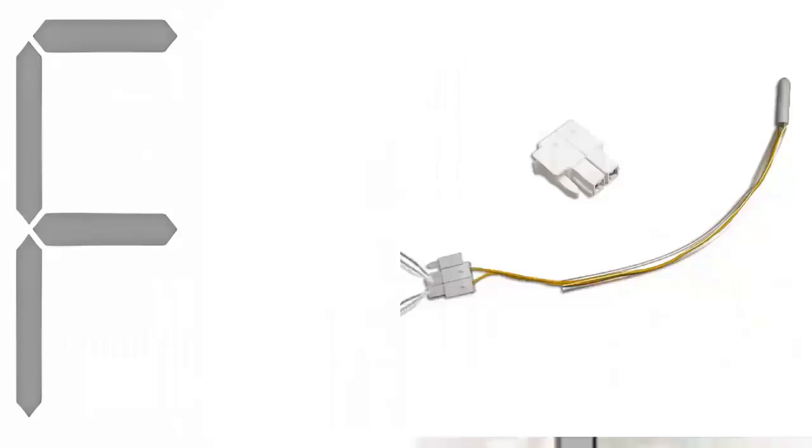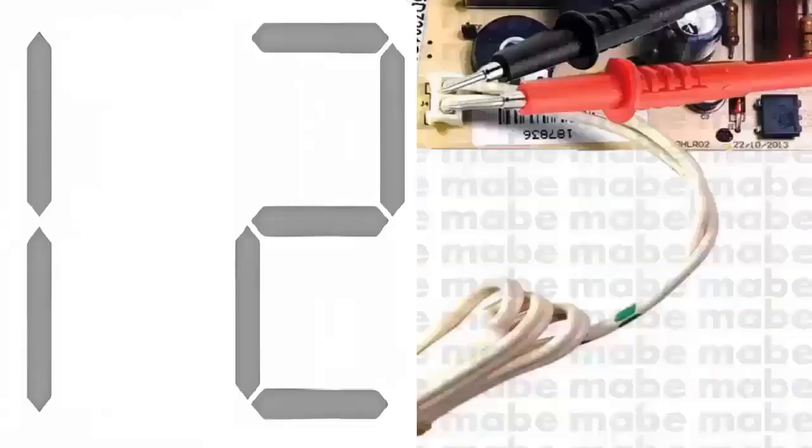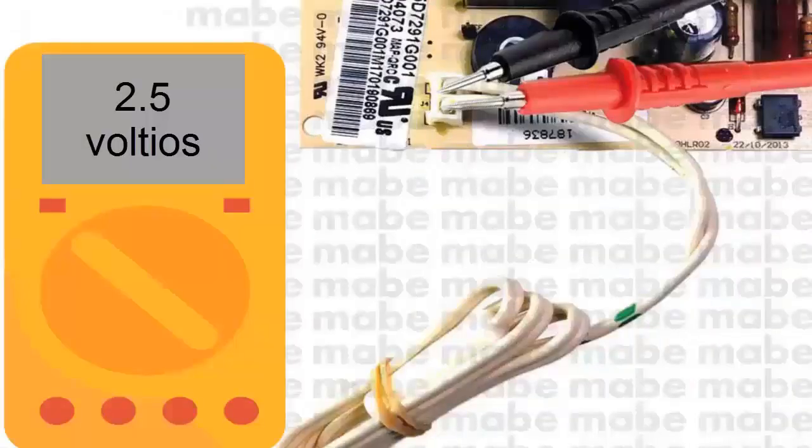F. The resistance value should never be 0 or infinite. G. With the sensor connected and the electronic board powered on, measure the voltage supplied by the board, with the multimeter set to the DC voltage scale. This value should be around 2.5 volts.